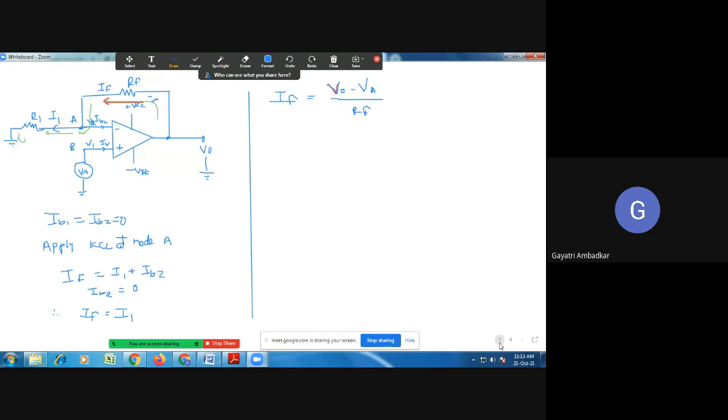And in this case, we are giving input to the non-inverting terminal. So whatever gain we got, the same thing we will get here with this circuit. Okay, but I am deriving it by some different method. Remember, in all op-amp applications, apply KCL at this point and you will get the solution of most of the problems. Okay, so yesterday we learned the concept of virtual short and virtual ground. So do you remember what is that?